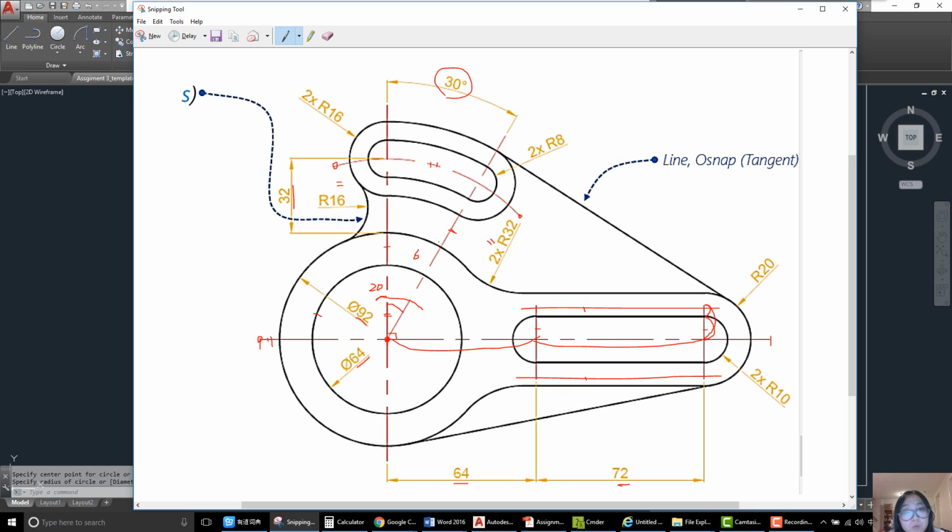And then I'm going to draw this arc and this arc. Let me see how to draw it. So this is an arc offsetting from this reference arc. So the offset distance here is 60, this radius, right? And this distance is the small radius, which is 8. So I will offset the reference arc by 8 and 16 to both sides to get the 4 arcs. Okay?